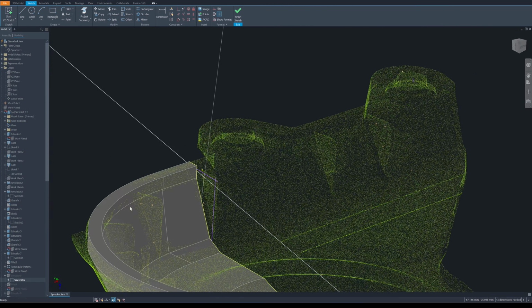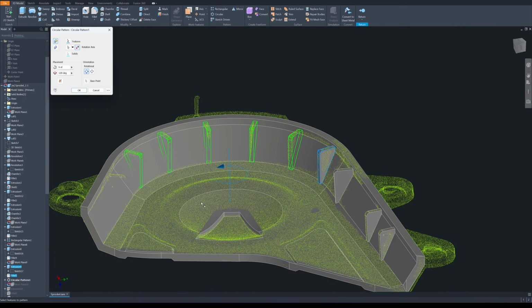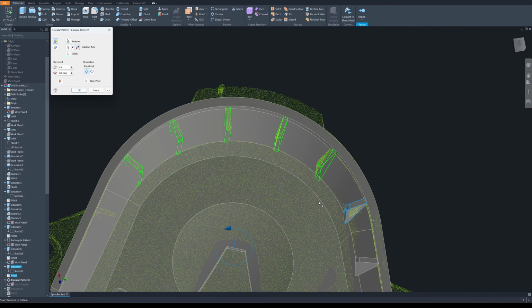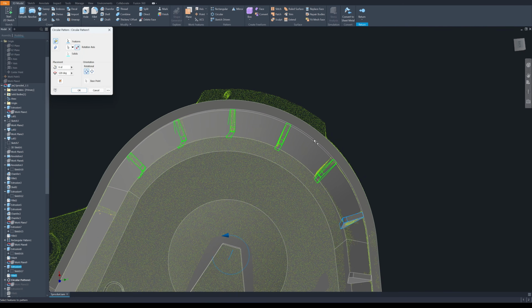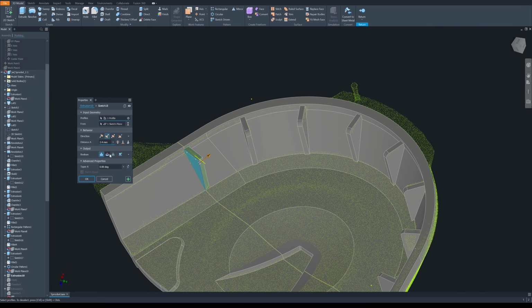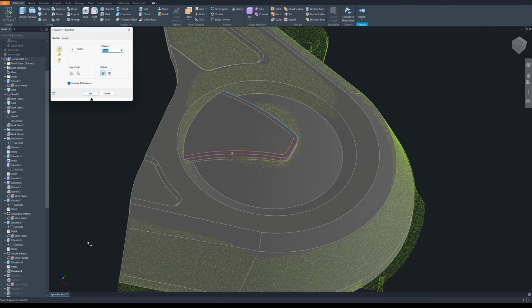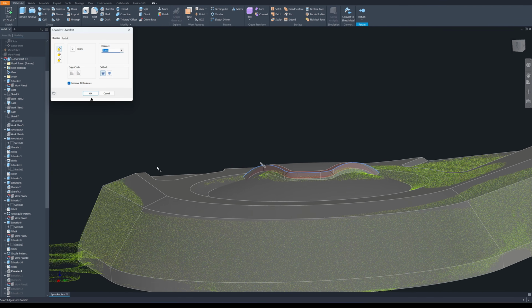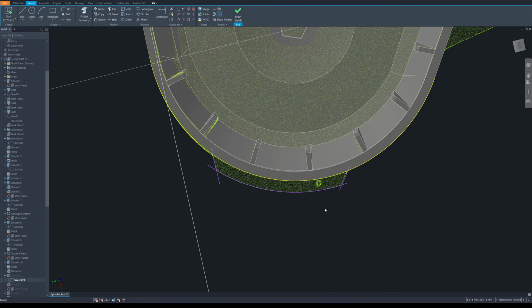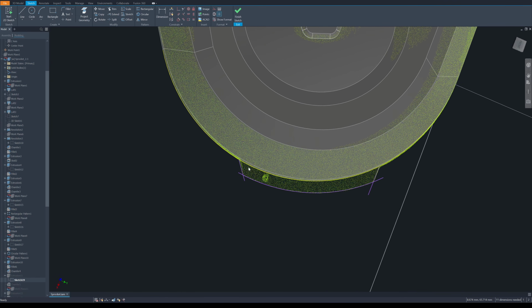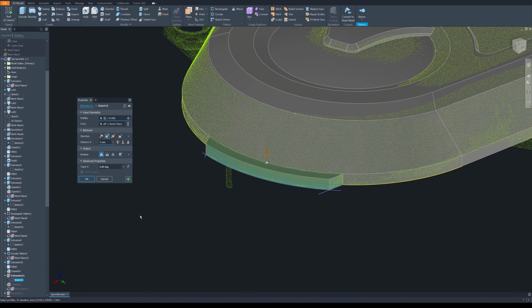Create a sketch for making a stiffener. And then I use the array command to do a polar array. There will be 6 stiffeners. So here, the final one, final stiffener. I make a chamfer in the front here to make it less sharp and easier to print. Okay, I create a sketch for the extension in the front. I make an extrusion of 5 millimeters.